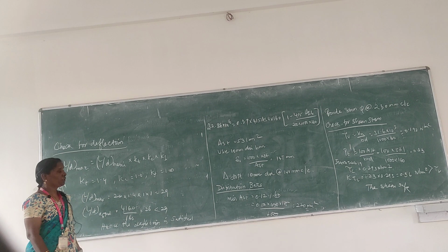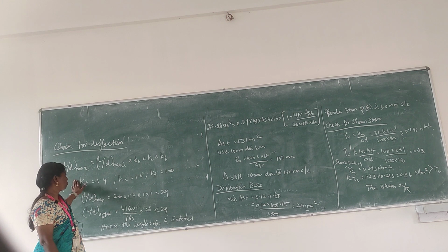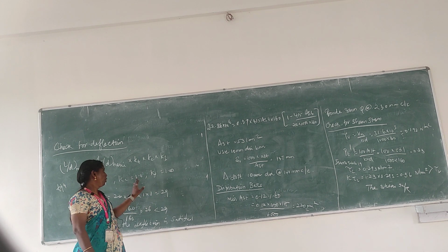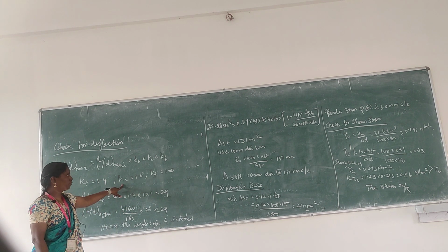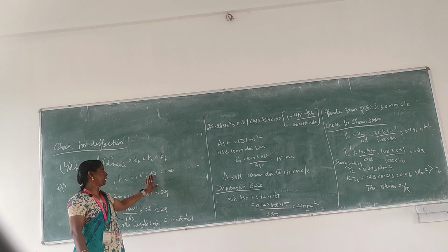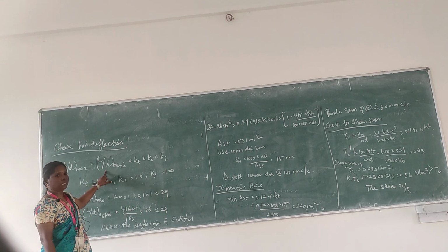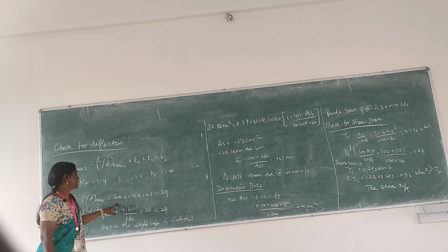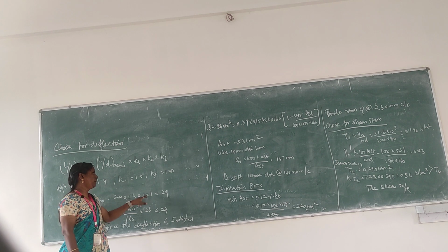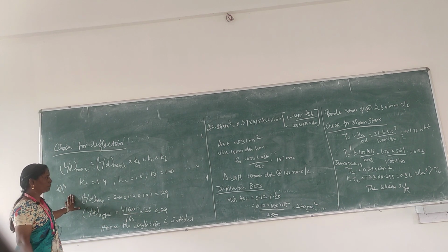So, what is meant by KT? As per IS 456 figure number 4, KT value is 1.4 according to the percentage of reinforcement. KC is 1, because it is under reinforced. For an under reinforced section, KC is 1. For a simply supported slab, the KF value is 1. So, altogether L by d maximum equals L by d basic, which for a simply supported beam is 20, and then KT value is 1.4, KC is 1, KF is 1. So, altogether 29. We calculated L by d maximum as 29.